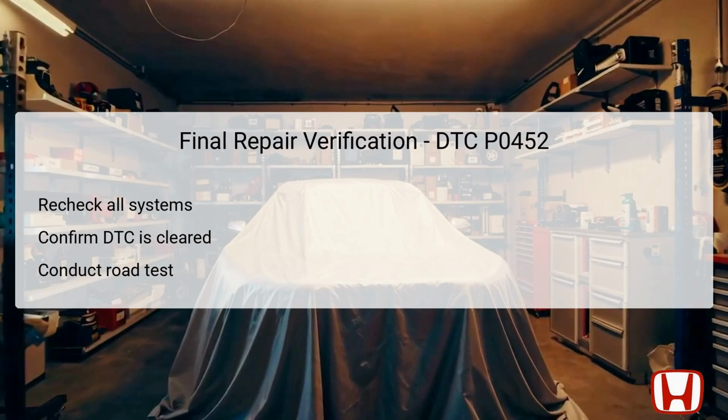After completing all troubleshooting steps for DTC P0452, it's essential to conduct a final repair verification. This verification involves rechecking all relevant systems to confirm that they are operating correctly and that any repairs made have resolved the identified issues. Confirm that the diagnostic trouble code has been successfully cleared using the HDS, ensuring the vehicle is not currently exhibiting any faults.